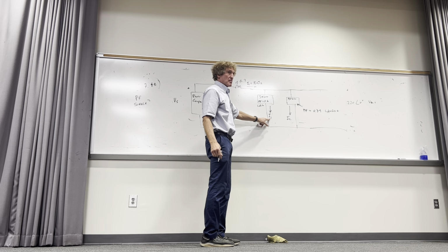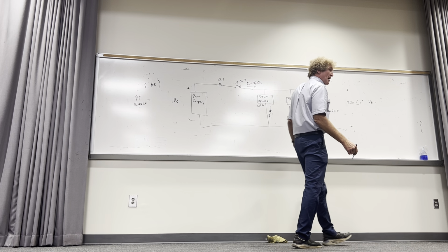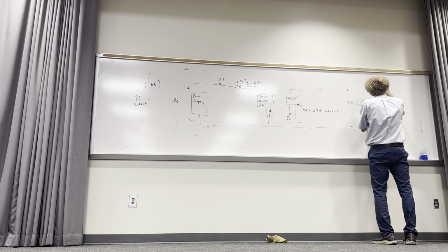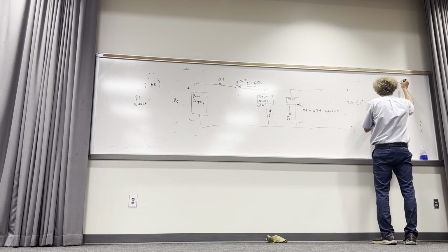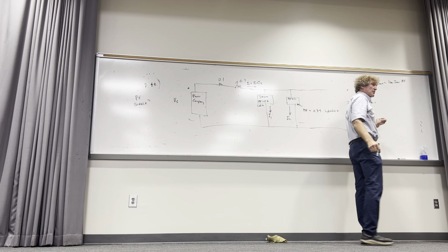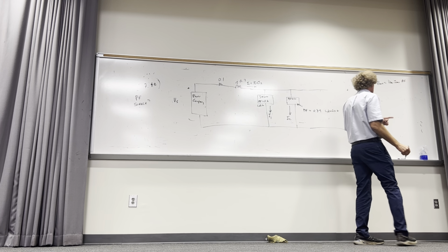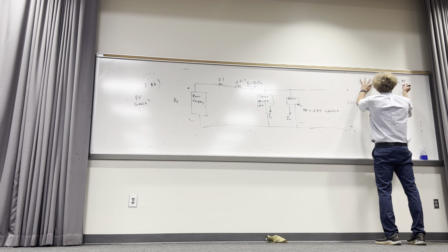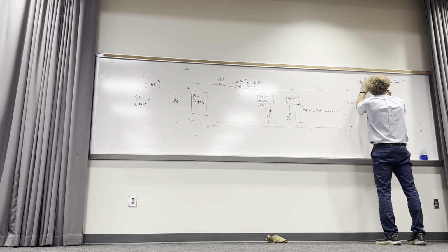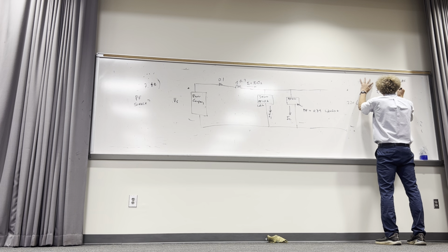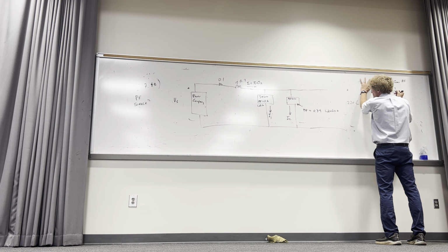All right, so let's start with this one. How do I get this current? And again, remember, we have average power given. So remember, you know P_AV is equal to V_RMS times I_RMS times the power factor. Do you agree with that? We're going to get the magnitude of the current first. So what's the magnitude? This is going to be for I1 right there. I can say that therefore I1, that current would be the average power, or 30 kW, divided by the line voltage, which is 220.